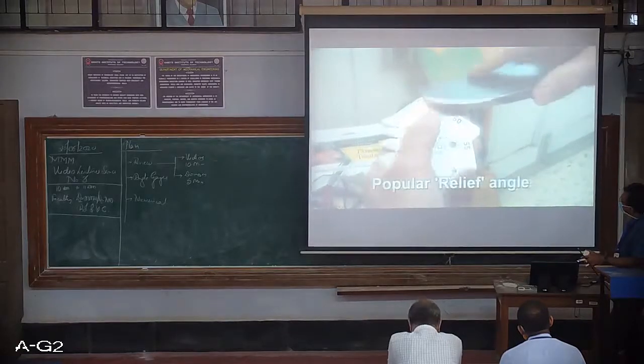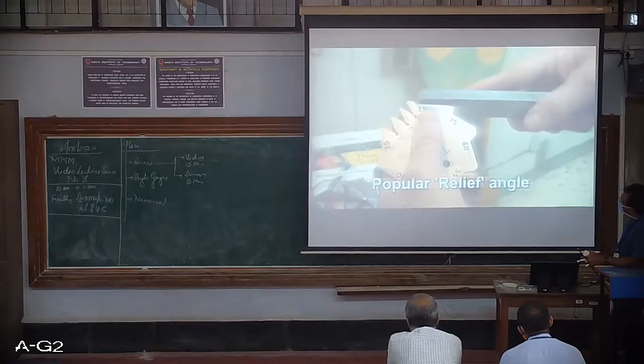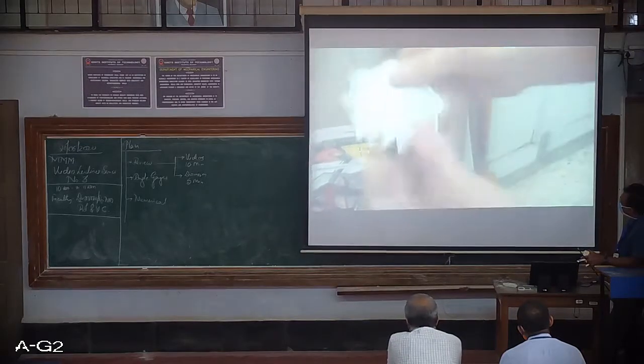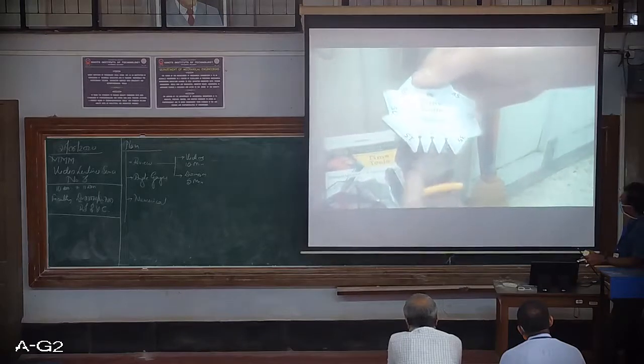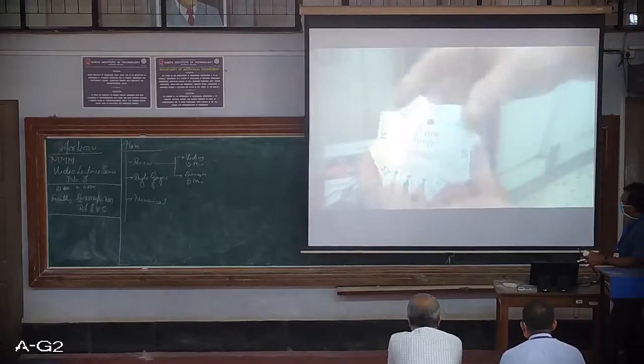I have 75 here, and then the relief grind up here, which is so tricky for everybody, I have it right there so you can see it's 15 degrees. And the neat thing is then you can take your parting tools and stick them up in there, and your skew chisels and stick them up in there, and they don't dull the tool points.